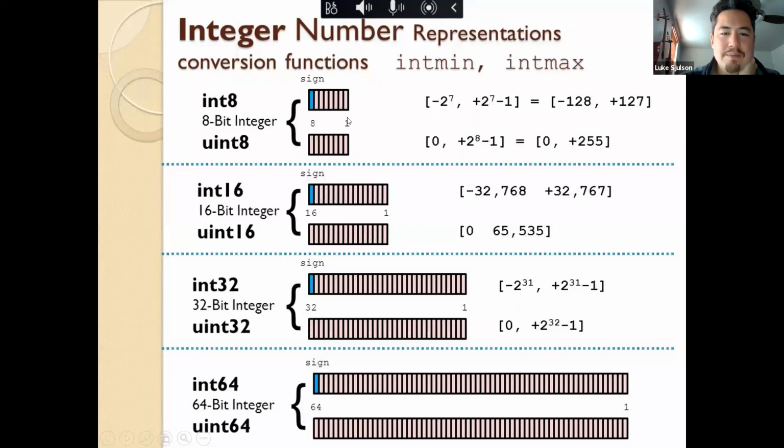8-bit A to D conversion is probably most common in cameras, where if you have an image, like an RGB image, they'll say 24 bits per pixel, most common image formats. What that means is that there's 8 bits for red, 8 for green, and 8 for blue. So at each individual point in the data, there's a value, and it's usually uint8, a value between 0 and 255 for how much red is in that pixel, how much green, and how much blue. Whereas for other stuff, like electrophysiology, it's usually higher than that.